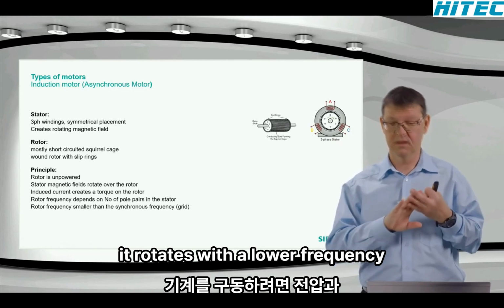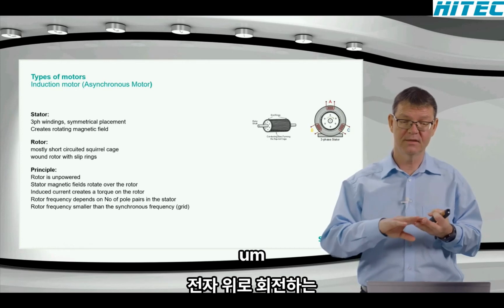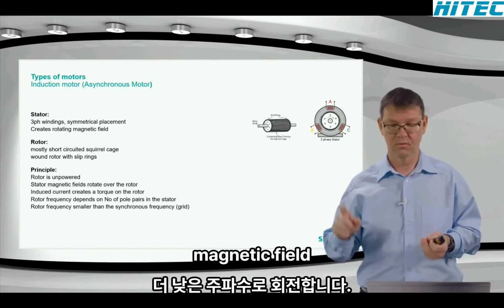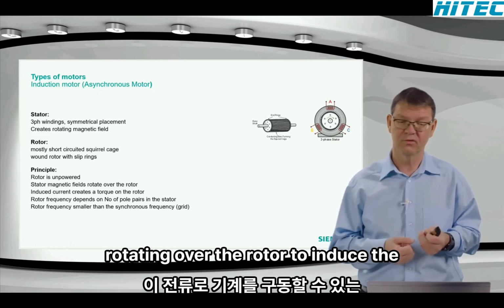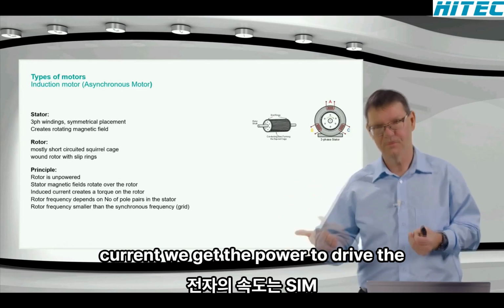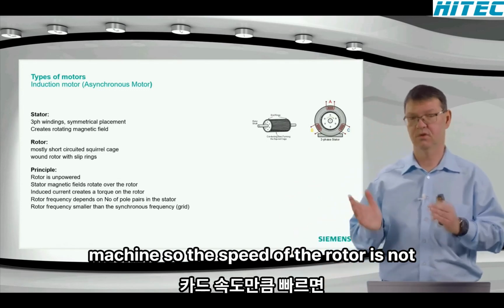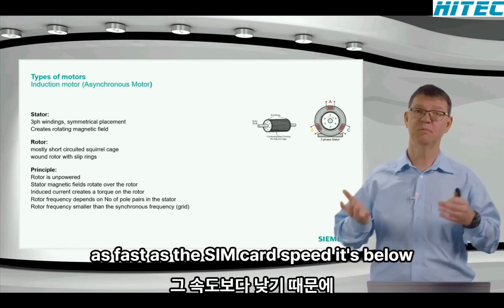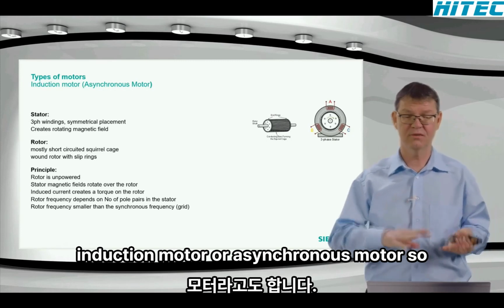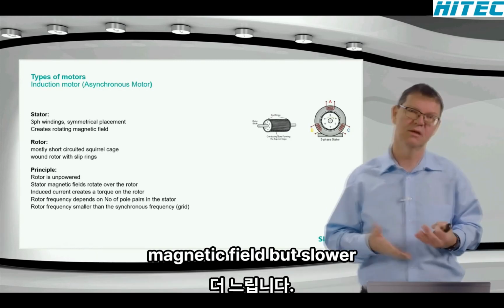It rotates with a lower frequency because to drive the machine, it needs a magnetic field rotating over the rotor to induce the voltage and the current. And with this current, we get the power to drive the machine. So the speed of the rotor is not as fast as the synchronous speed, it's below that speed. Therefore, it's also called induction motor or asynchronous motor. So the rotor is not synchronous with the magnetic field, but slower.